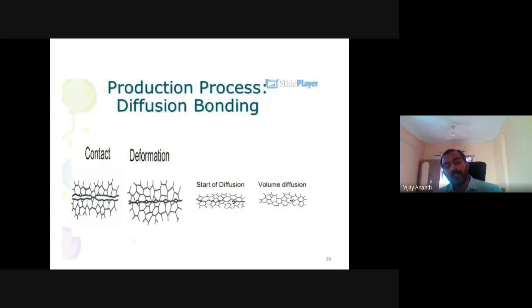Another main advantage in plastic forming is that diffusion bonding can also be done through it. In the normal diffusion bonding process, we have two sheets, and high pressure is applied on the top and bottom of the plates in a furnace, then it is formed. But here we are only applying air pressure.